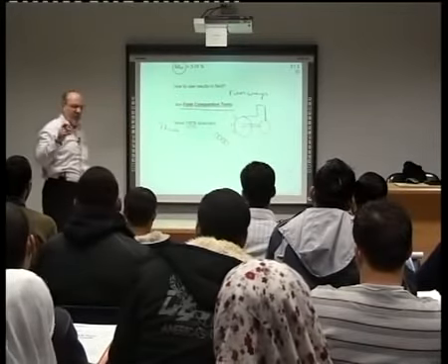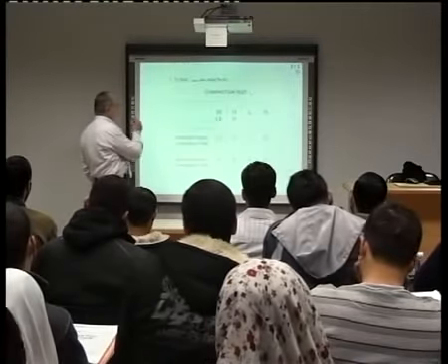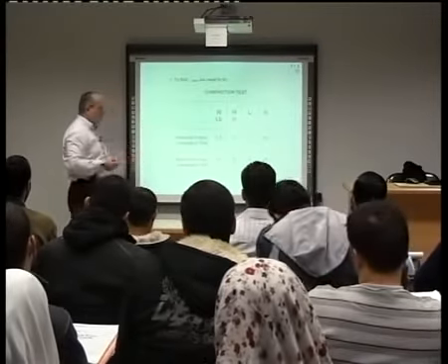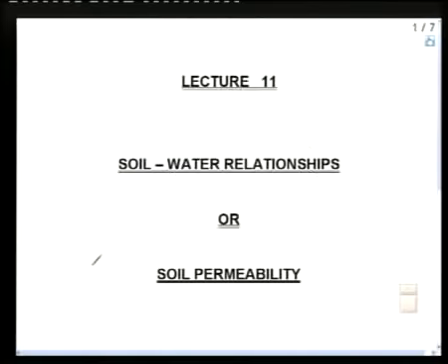But what you need to know is that from the Proctor, from the standard Proctor or modified Proctor, I can calculate the energy, okay? The energy. And from that energy, I can go to the machines, okay? And from then I can choose which kind of machine I will use, okay? We will end up with this in speaking about compaction, and we go now to another subject, another chapter, which is